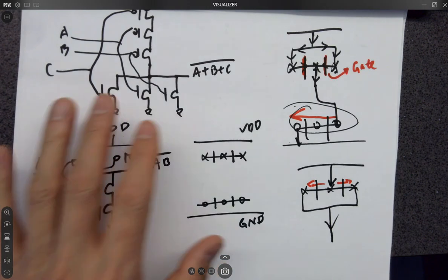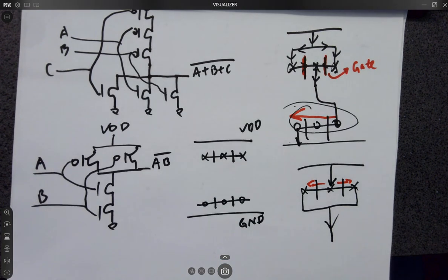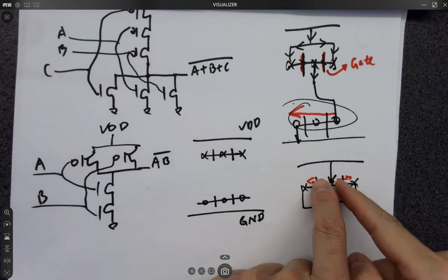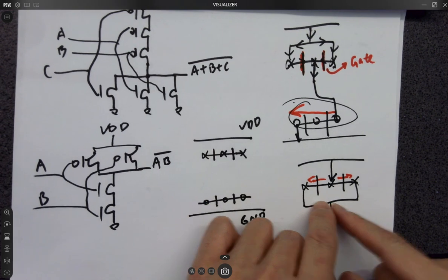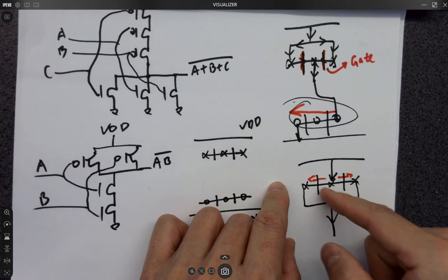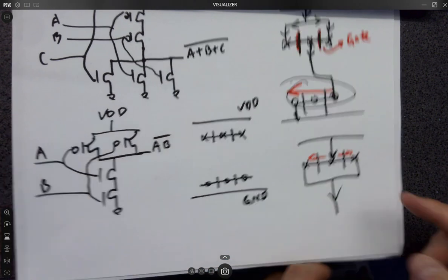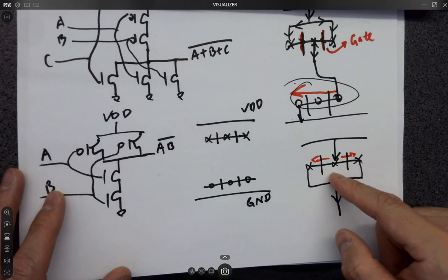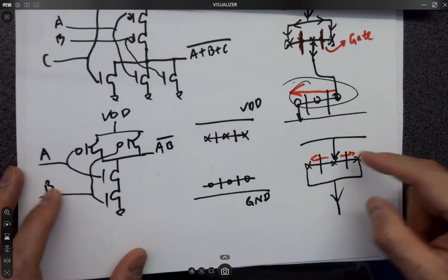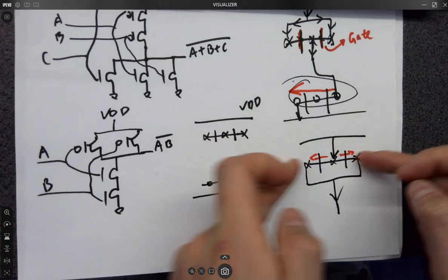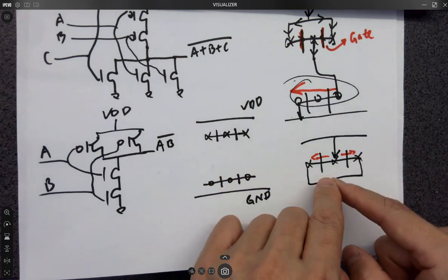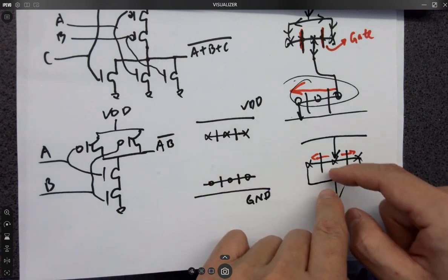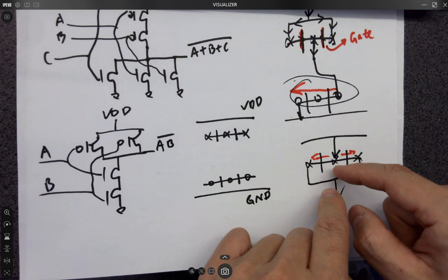I mean, for this example, it probably doesn't matter because the circuit is so simple. But in the future, you have to consider that if you have more nodes in the middle, and if you close it by this wire, it gives you a hard time to wire everything out from the middle. You know what I mean? There's nothing you need to connect it to here because you already have this wire on the top. But in the future, you have a pretty long string of transistors, and there are a lot of nodes in the middle. If you close it that way, you have to find a space in the middle to build the vias. It takes space.